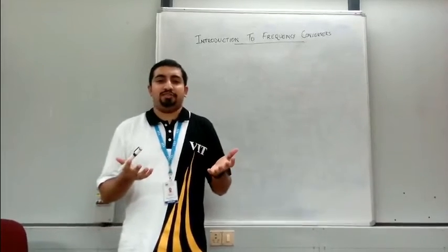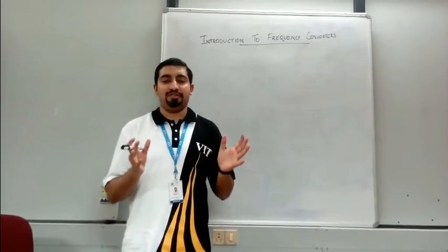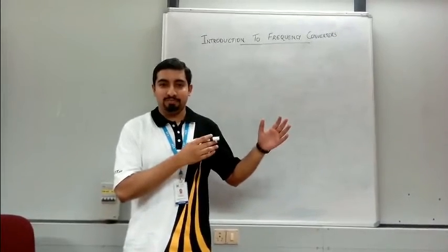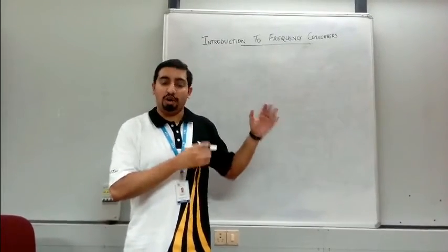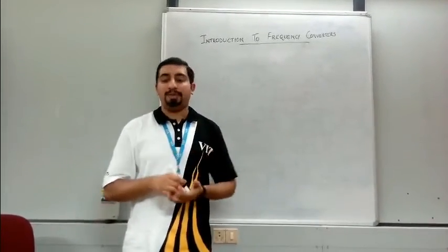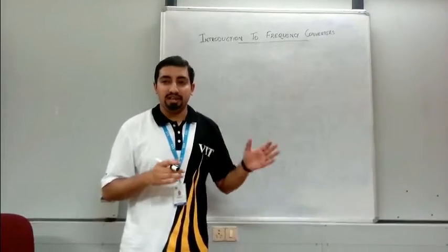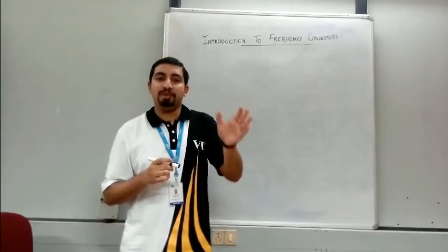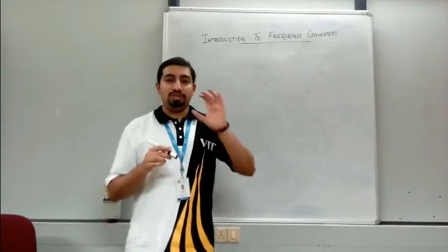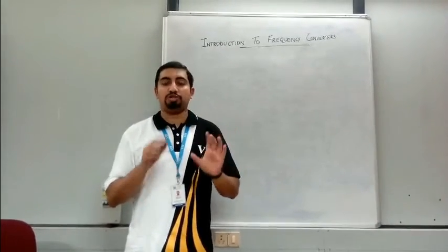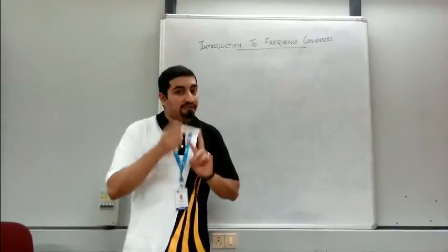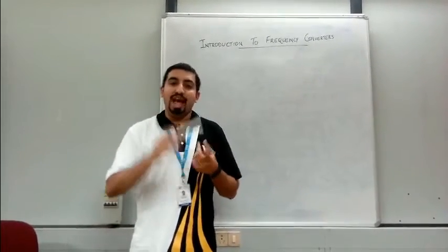Now what is a frequency converter? It's a very simple device. A frequency converter converts the supply mains AC, that is your three-phase AC or single-phase AC depending on which application you are using, to a variable voltage and variable frequency output. Now this variable term is very important because it has two components. One is variable voltage, the other is variable frequency. So both frequency and voltage are variable in this case.